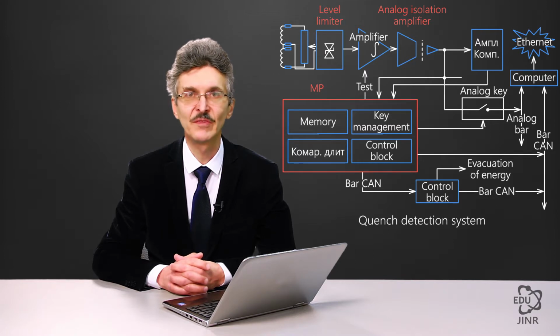Firstly, the supply system must not cause any interference with the power system. Secondly, the detector has to be isolated, both from the main power supply and from the ground. And lastly, it has to offer a particular set of service functions. That is, to record the signals of voltage development during the occurrence of a normal conducting phase.